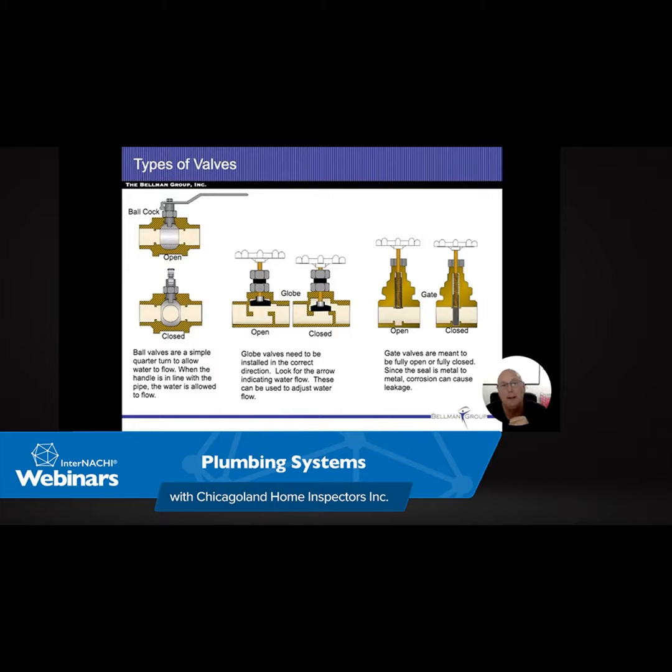We let those pipes be a straight run all the way through the roof, so that if any sewer gases do come up there, we let them vent out through the roof. But the building trap in here prevented that, at least on that line. Obviously, the one that's coming to the right of it, and they did merge together, sewer gases would still come up there. But it was kind of a no-brainer, when somebody puts duct tape around a pipe and a bucket underneath there that has water in it, there was a pretty good chance that it's leaking, and this one obviously was leaking when we came with it.